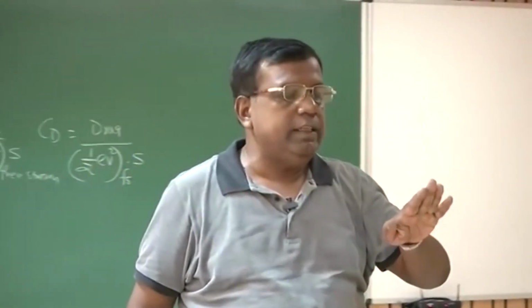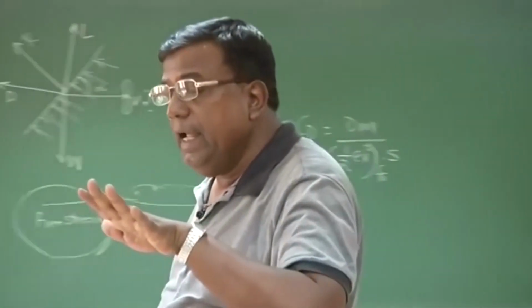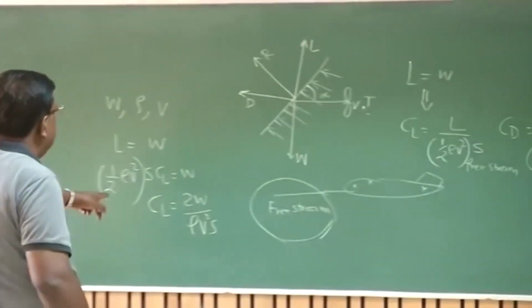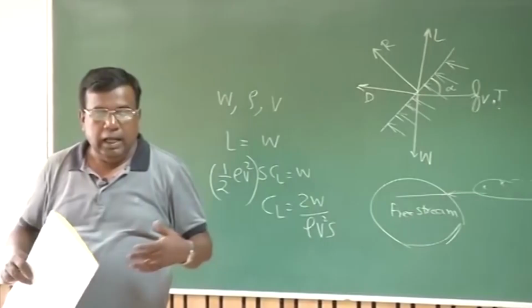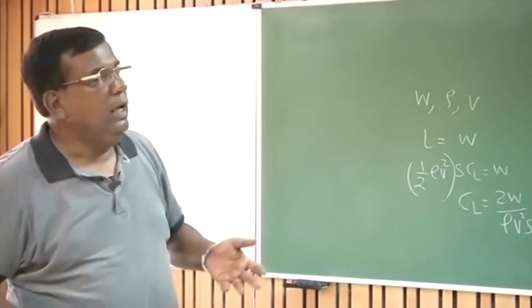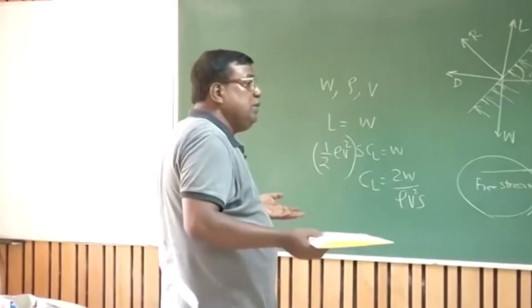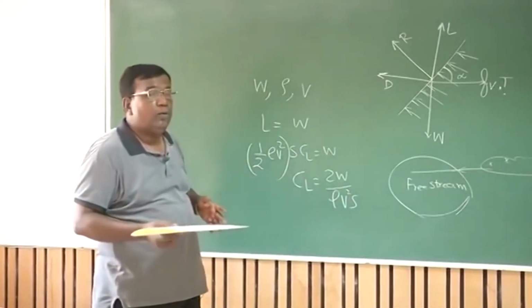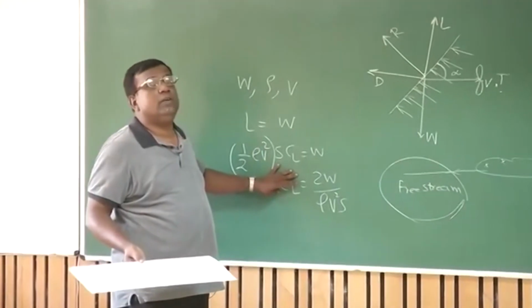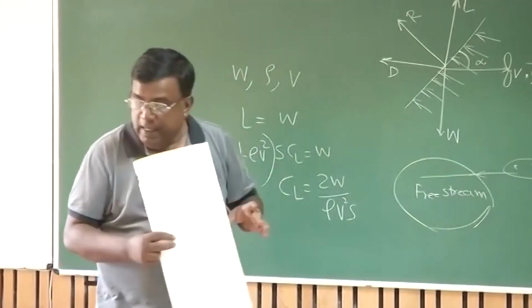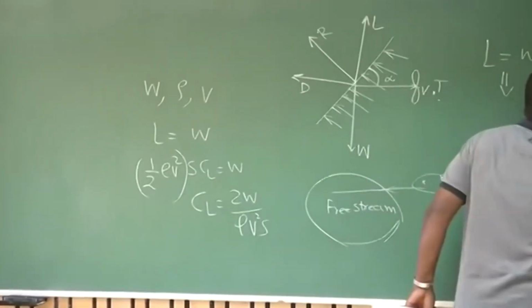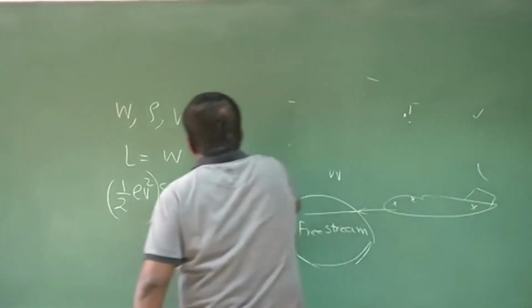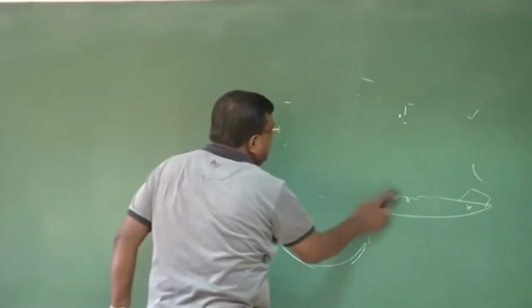I will be turning this plate at an angle or turning the airplane at an angle, so that the total CL of the aircraft is what is dictated by this CL. And how do I do that? Because I know the airplane has a wing, has a tail, and at angle of attack they produce lift, the fuselage produces lift, the total lift and total CL should be equal to the CL required. This part we have already covered. In covering this, we have also spoken about the finite wing, and quickly I'll go through that. Finite wing we understand.